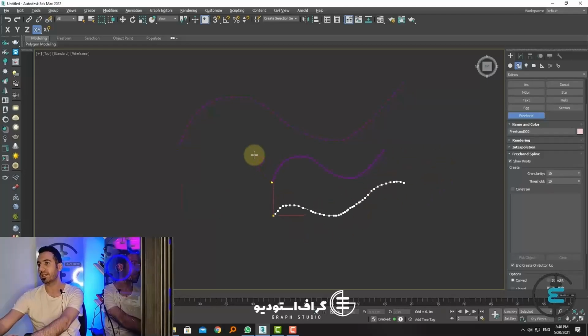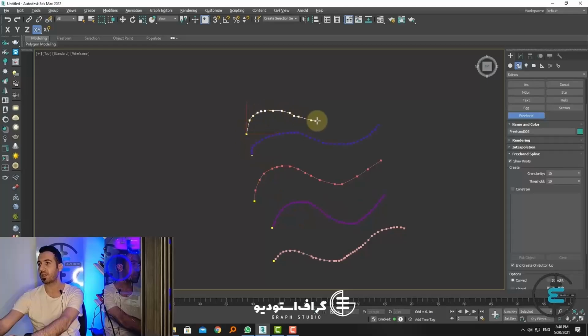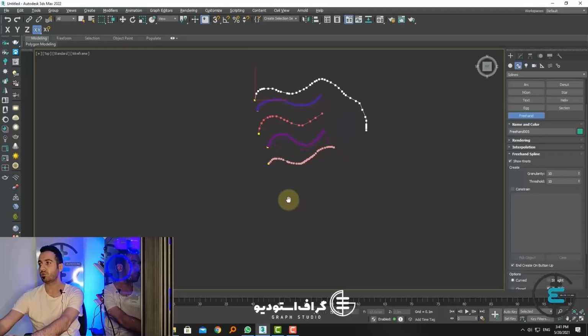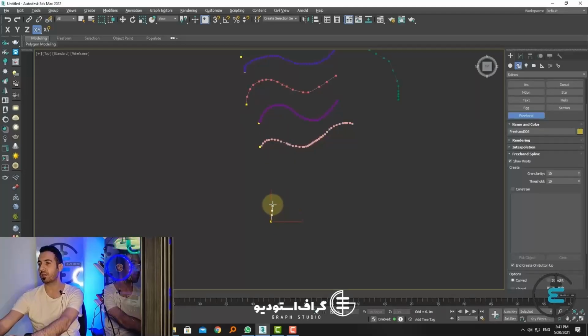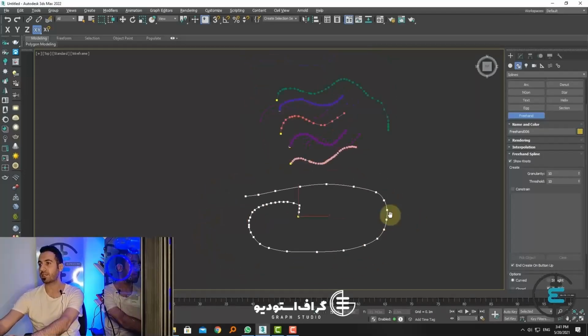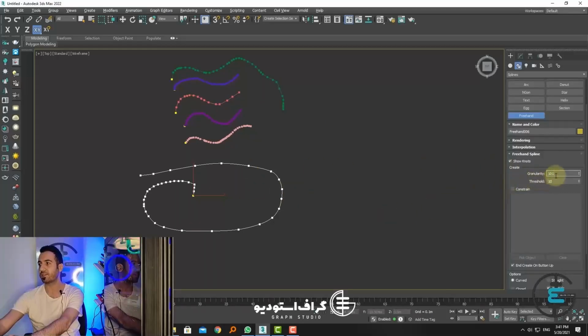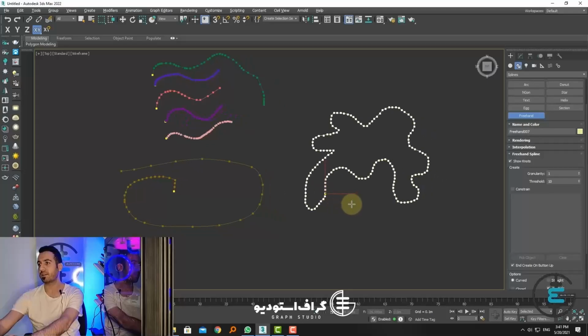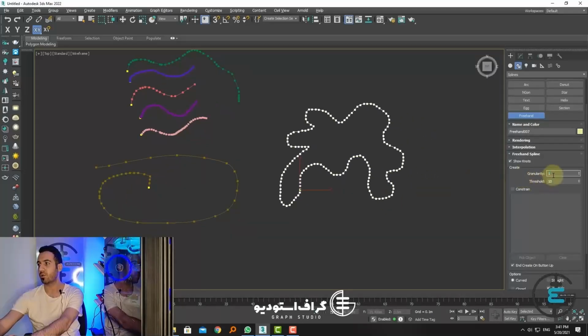Well, as you can see, this is our drawing method. Now if I make this one, you see that the more this number increases, now the maximum will be, I think, 10, yes. When this number increases, the number of these nodes somehow decreases as well. In a way, this decrease seems to have its sensitivity. See, I drew this now with 10. See that the number of nodes is less. But when I put this on 1, you see how many nodes there are, and the sensitivity is higher. Now, depending on the work you want to do, you can adjust your freehand and your number. Well, I'll leave this at, for example, 5 for now.